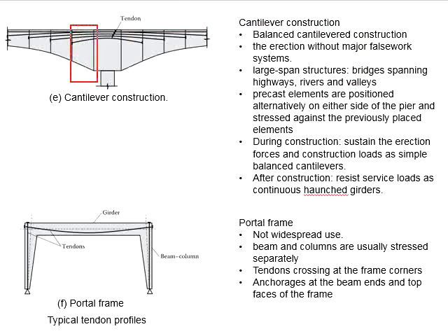Now that you have precast members to be installed together with the pier, you will need to post-tension the tendon here so that the members stay attached to the piers. To prevent undesired bending moment during the construction, we will install the two members together so that the final resultant is still a vertical force acting along the neutral axis of the pier.